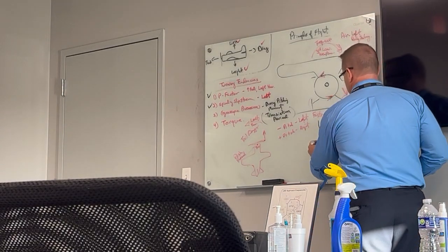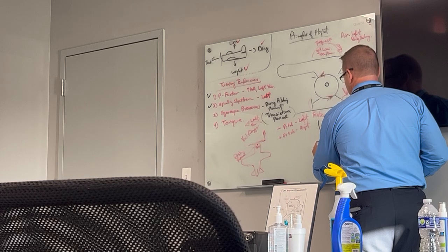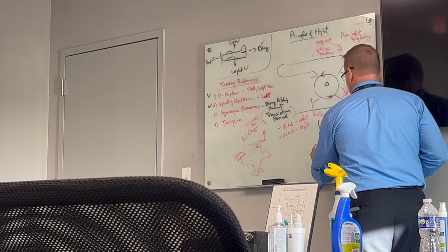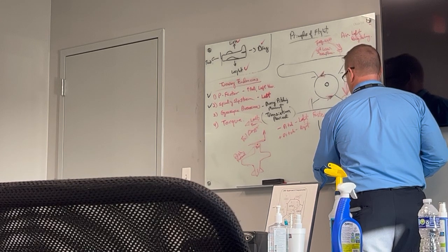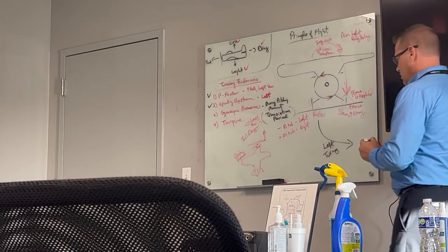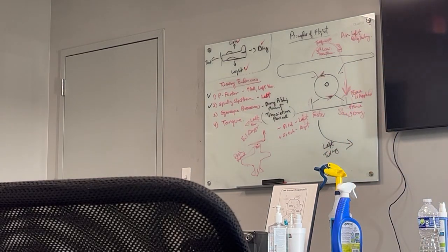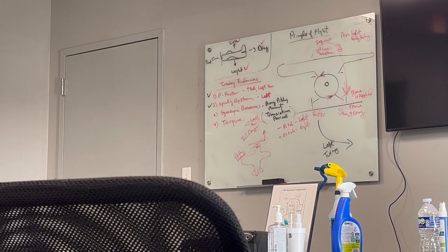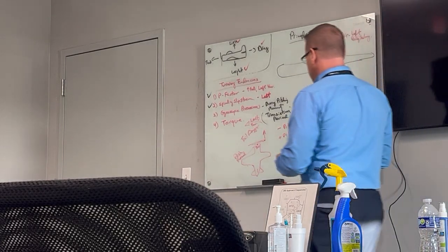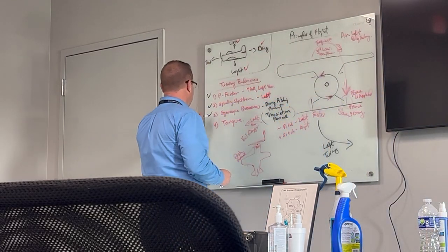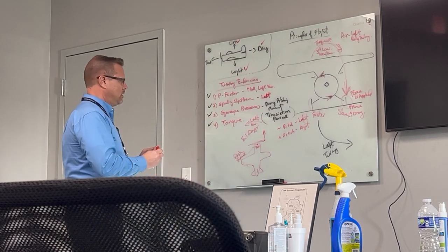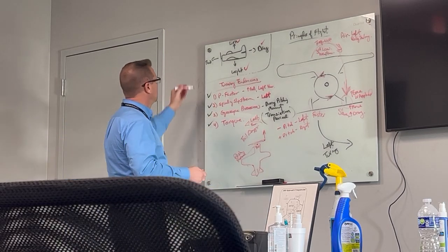This is going to be a left turning tendency on the ground. It's a left rolling tendency in the air, but it's a left turning tendency on the ground because the ground's in our way. So that's that one, and that one, and thrust.